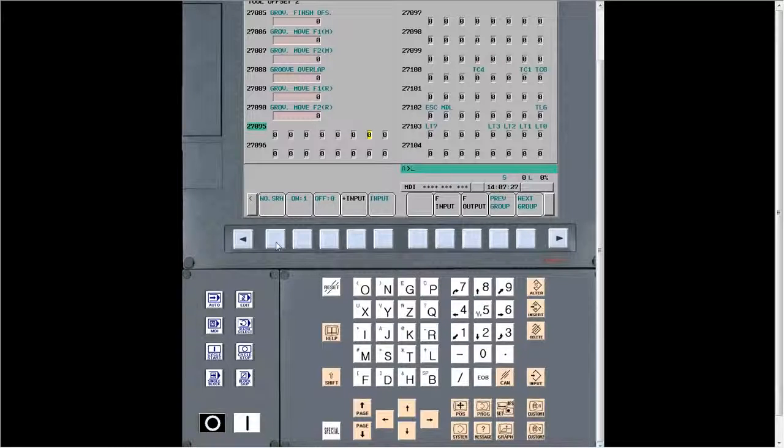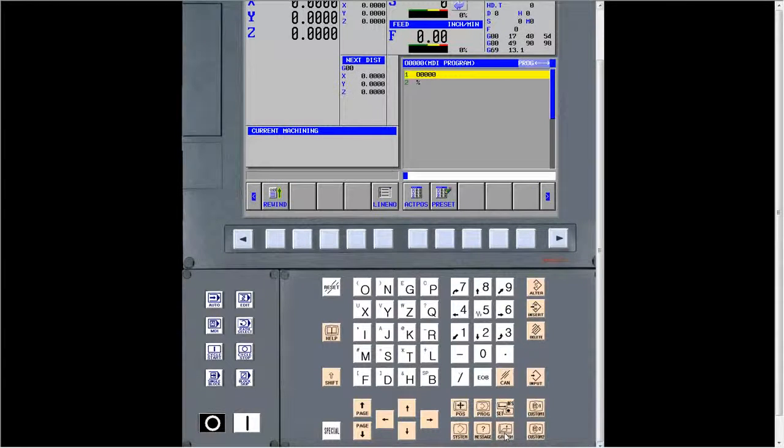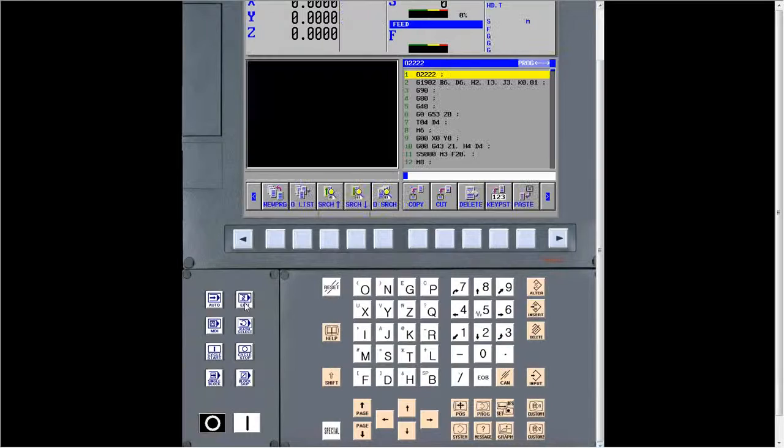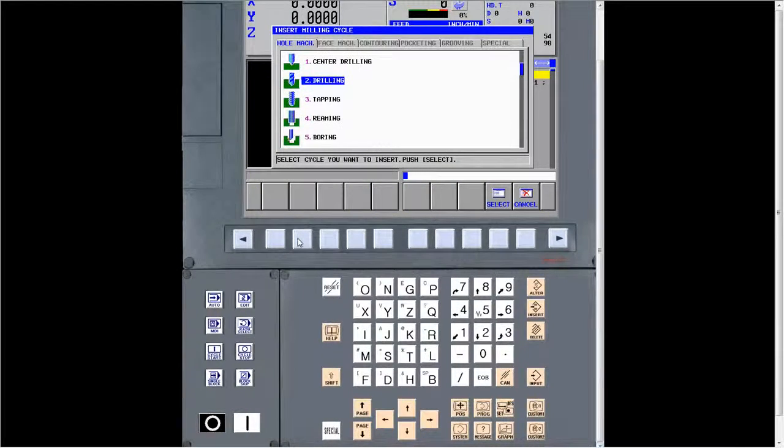For some of you out there that don't understand how Fanuc does parameters, you start from the right-hand side as bit 0, 1, 2, 3, 4, 5. And you can set it on with a number 1. It puts a 1 in there. Now when we go back to our Manual Guide I, back to Edit, and we go right shift, back into our cycles, now when we arrow down, we have another cycle there, and it's thread milling. So that's how you turn it on.